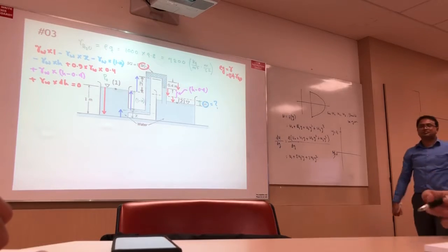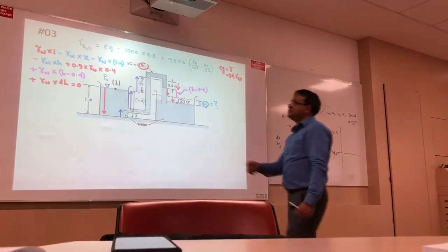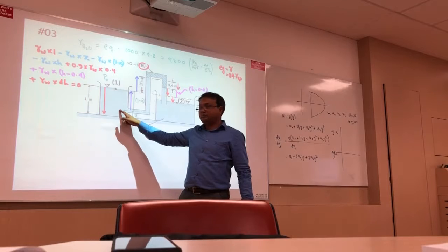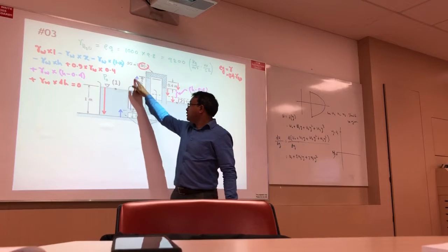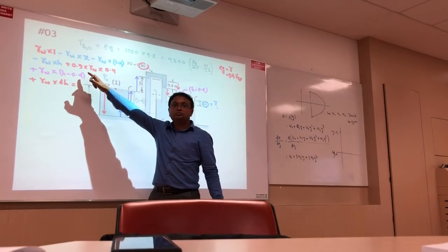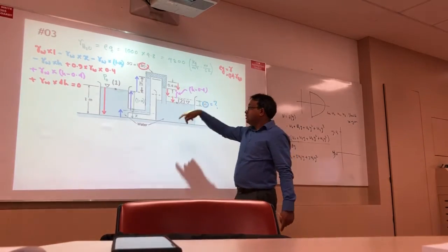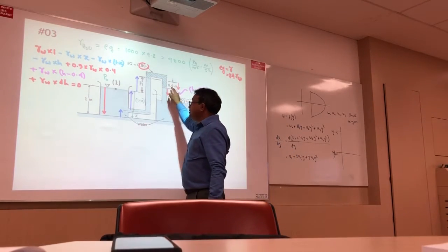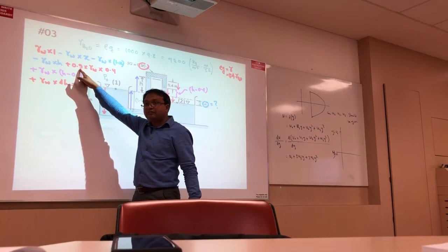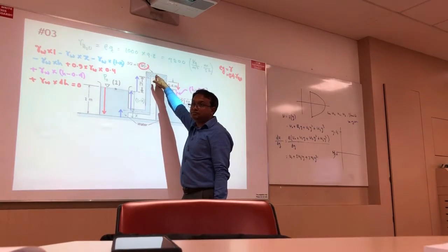Then you can get it. Understand? Very simple. From here to here, positive. From here to here, negative. From here to here, negative. Here to here, negative, right? Here is all water. I put gamma w, or you can write rho w g, same value. Then from here to here, positive. But here I write specific gravity, right? Why? Because another fluid.